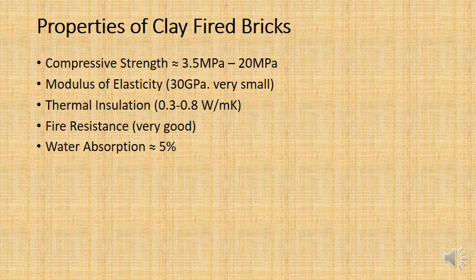So let's talk about some properties of clay-fired bricks. The first one is compressive strength, and it's quite amazing that clay initially, when it's just mud, has very little strength, maybe only half a megapascal, but once you heat it up and you get all those chemical bonds and reactions happening, it's going to end up with a compressive strength of anywhere between maybe 5 to 20 MPa. That's pretty good.